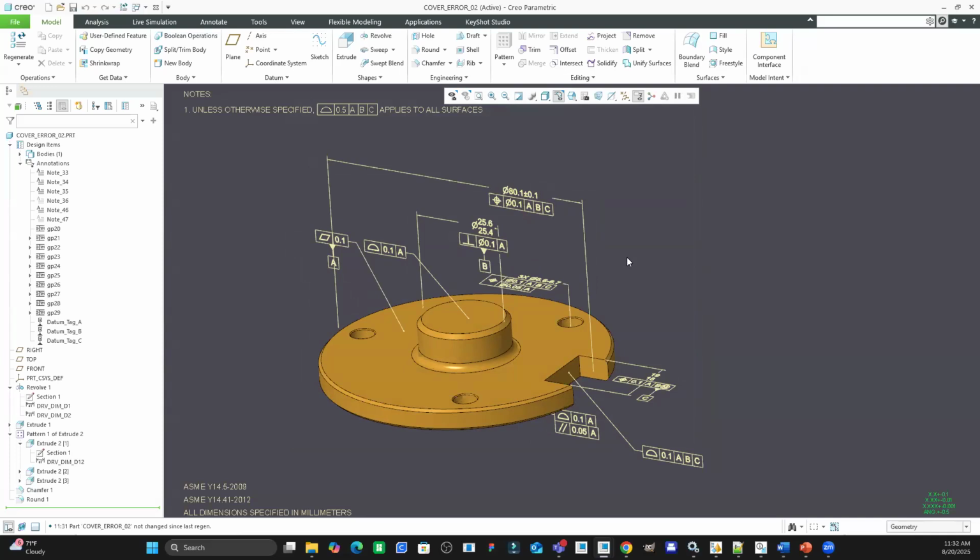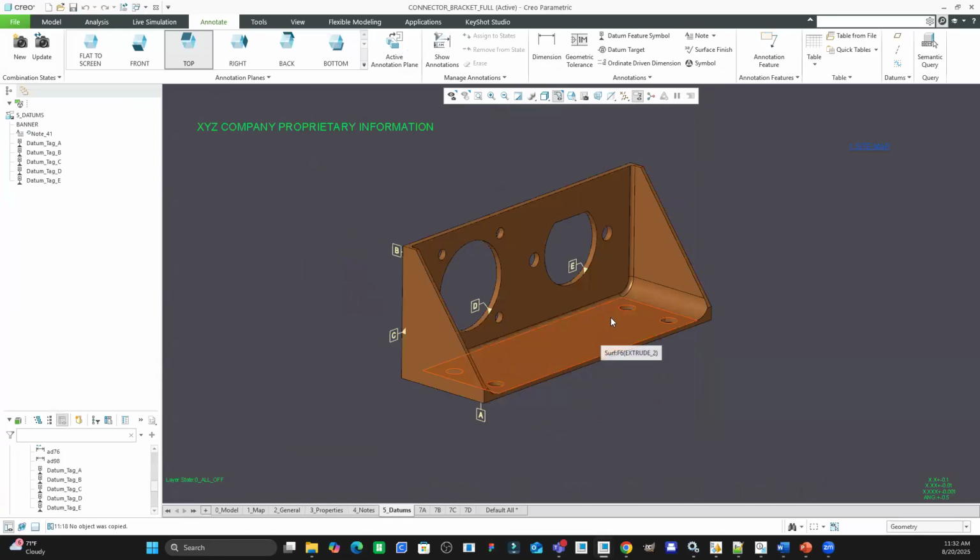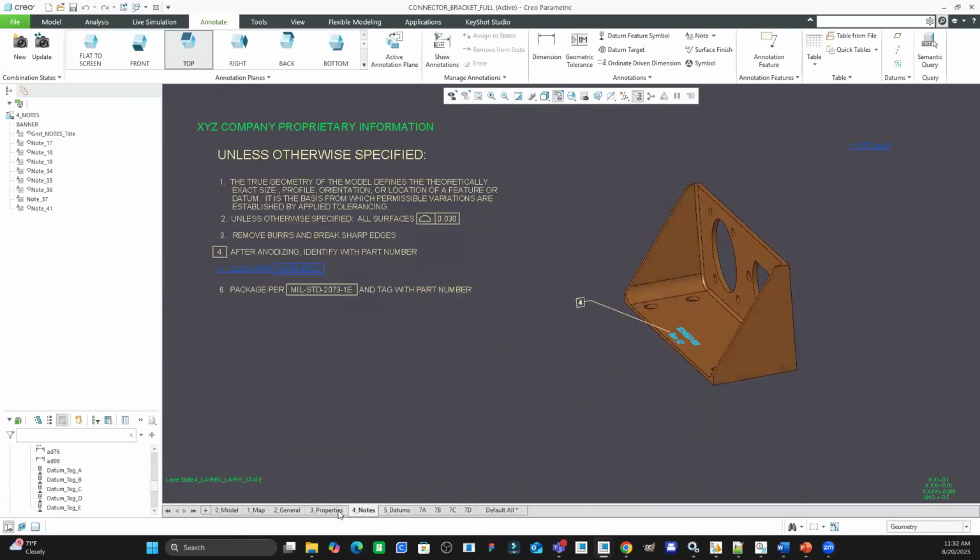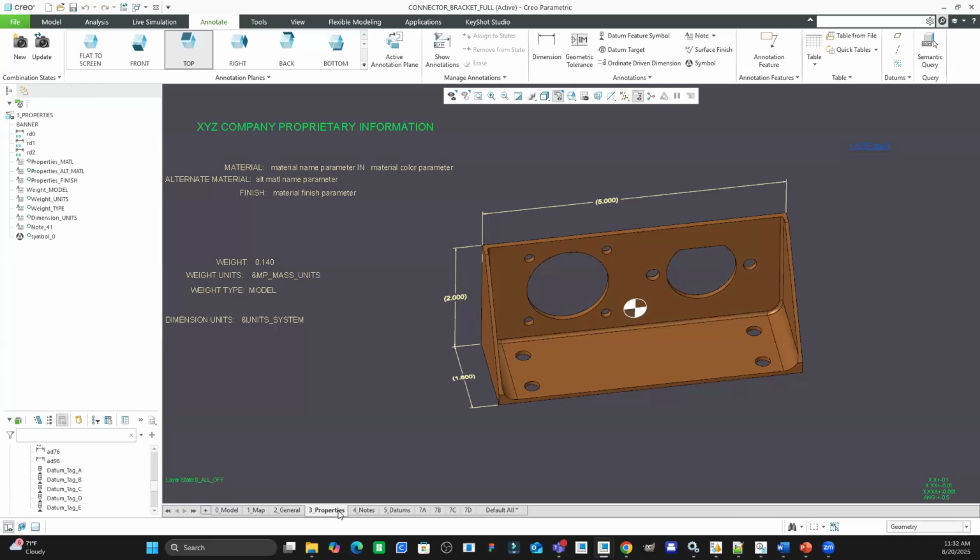that you apply to the model, if you use that model-centric approach, is very powerful, right? Not just because you're able to create dimensions or annotations and notes on the model, but because all this information can be shared, right? It can be shared in Windchill and opened up in Creo View and marked up by another engineer or even yourself, just as notes to yourself, like, hey, I think I should change this. Let's go back and rework it. This PVZ file can also be shared to Creo Illustrate to create work instructions for the shop floor.